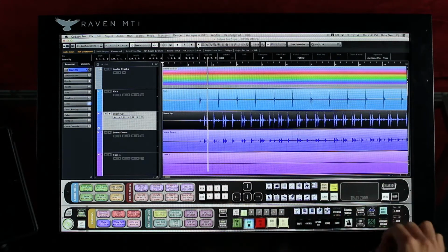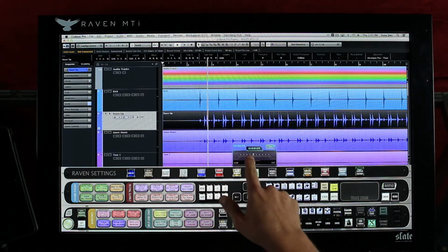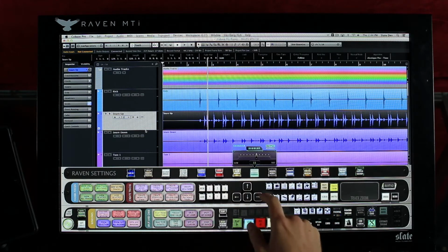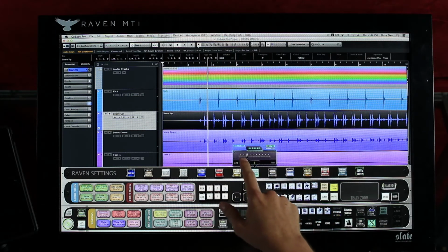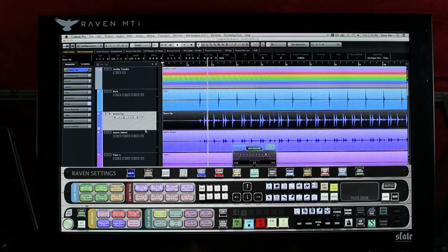The nav pad is also capable of adjusting the response specific to the user's preference. Go to Settings on the Raven toolbar and press the nav pad response button. Adjust from 1 through 20, 1 being the slowest response and 20 being the quickest response. We have set the nav pad to default on Natural Movement settings. However, we have now included the option to invert the direction response by toggling to Inverse on the nav pad response window in Raven settings.